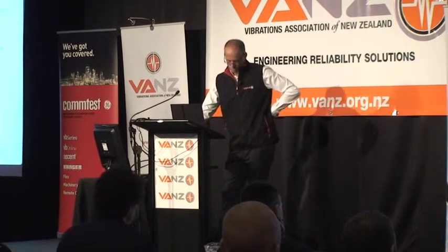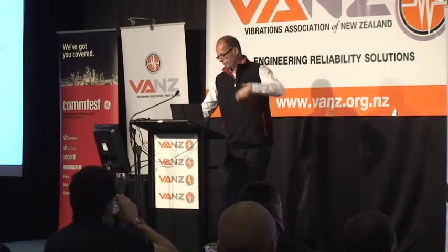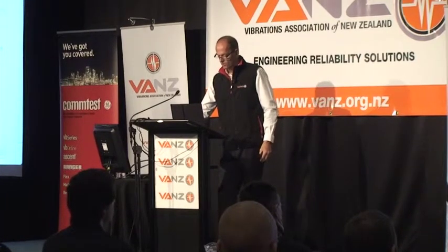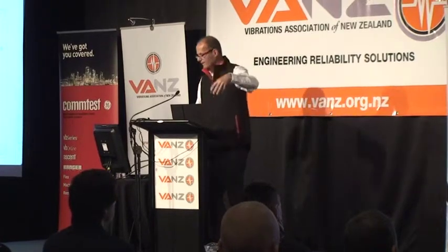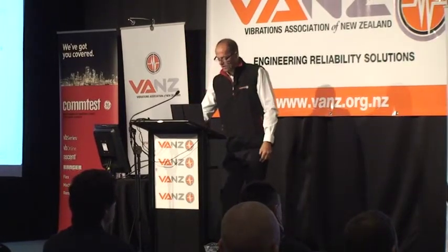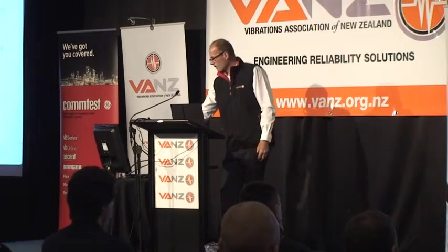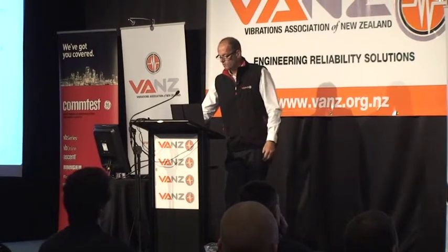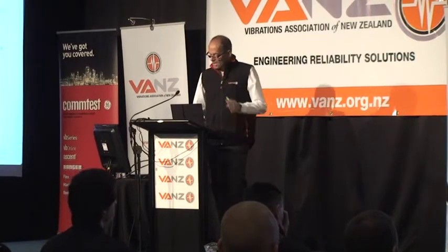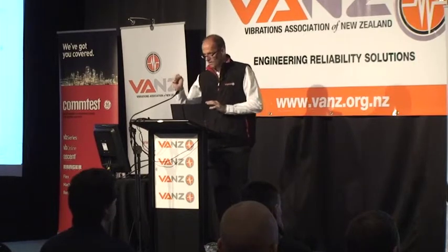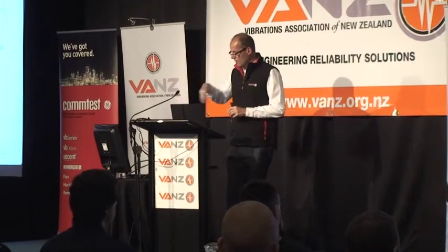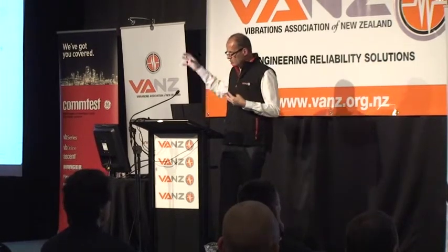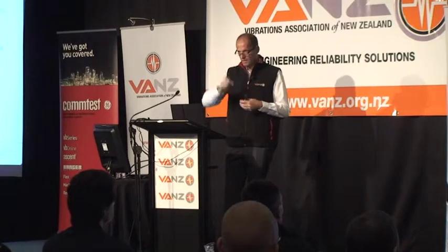Now what I'm going to do just quickly is say, well, there's our primary source of vibration, just the shaft turning. And if you look at the animation, you can see, even the shaft's wobbling a little bit. So, the wobble of that grey shaft is my grey sine wave. And just to keep it simple, we'll focus on the fan. So, we're not putting a sensor on those fan blades. It's just that vibration, the thump, thump, thump, as each blade goes by a reference point, if you like, is transmitted along the shaft through the bearing, and we sense it there.